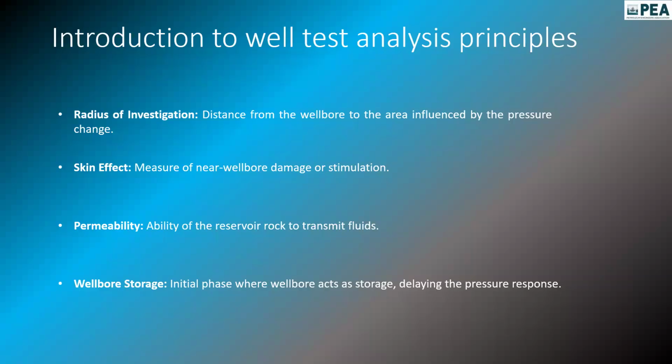In this annulus space, you have to hold these drilling fluids before opening the perforations. For that, we need these drilling fluids to possess a property called thixotropic property, which will hold all the drill cuttings there.